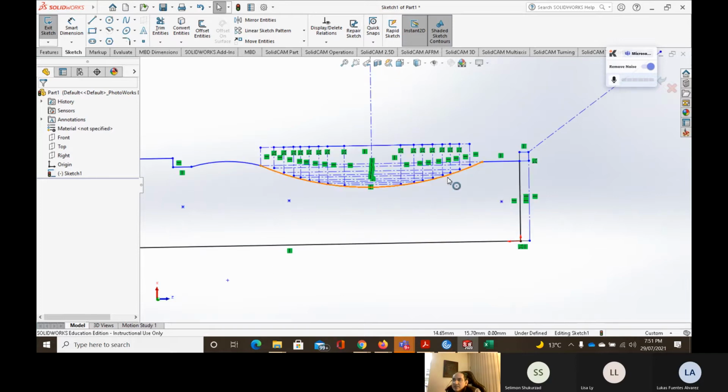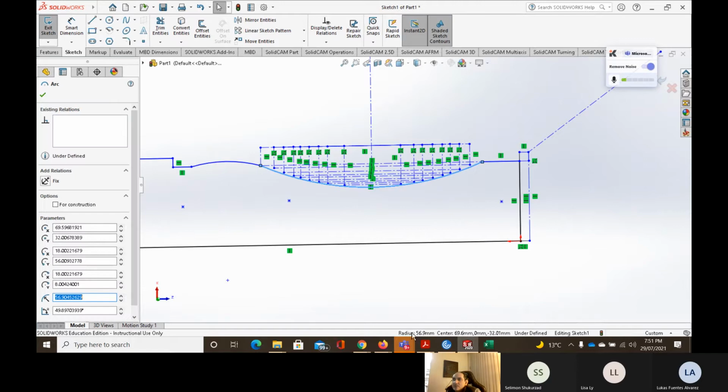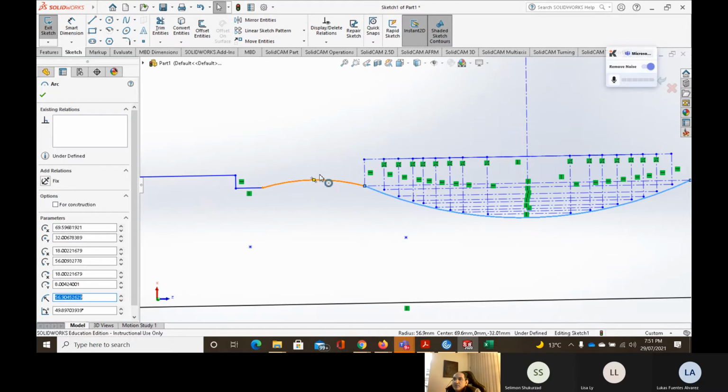Or simply I can use this radius, which is going to be 56 or 57, and the machine will make the cut for you. Just simply write down G02, define the end point, and the cutting tool will remove all the steps until we reach that point. Of course, the same process will be repeated on that side. Actually, on this side, we can do the cut directly because I don't think there will be too much material. So the cutting tool can move directly and remove it. And then we're going to have G01 and done.